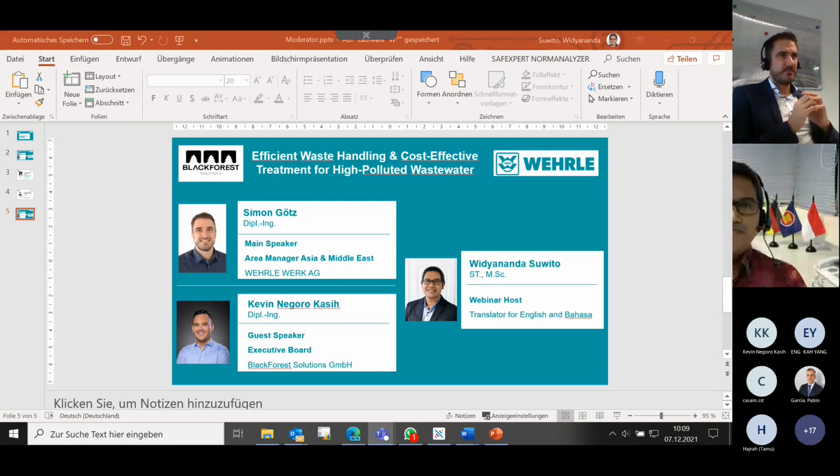So we are fighting against the biofouling through regular CIP cleaning, usually alkaline and acid, and also through this feed and bleed design, where we have a special pump to bring up a high velocity to make it more difficult to stick on the membrane. All right, so the CIP and also the feed and bleed system will try to combat the biofouling in a very good way. Yes. Exactly.